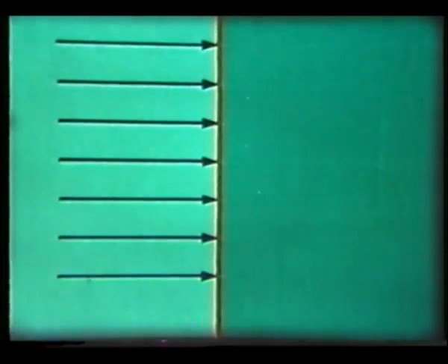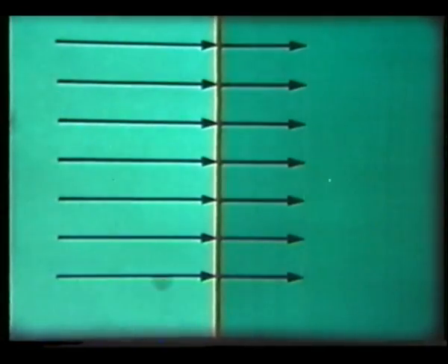But what if the disturbance is large? Such a disturbance is produced by a leading edge in supersonic flow. An oblique shock, the bow wave, is formed. How does the flow behave as it passes through such a shock wave? Consider first a diagram of a normal shock wave. This, at right angles to the flow, always slows it down from supersonic to subsonic. The speed is represented by the length of the arrow.